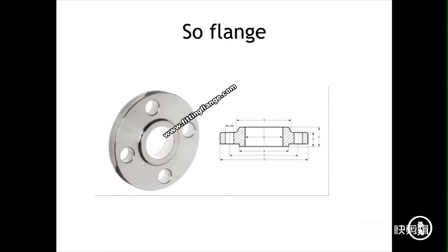Slip-on flange. This kind of flange is very convenient and very easy to be assembled for the workers. But there is too much workload to weld those flanges on the pipe system. It needs more welding rod, and slip-on flanges cannot resist high pressure and high temperature.